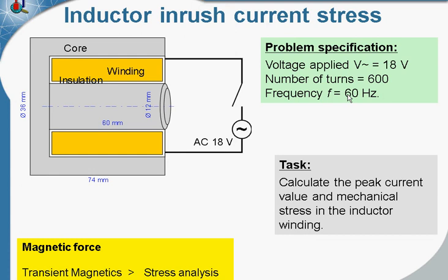This problem is essentially multiphysics. First, we should simulate transient magnetic problem to compute current versus time dependency and magnetic forces. Then we should pass magnetic forces to stress analysis problem to calculate mechanical stresses.